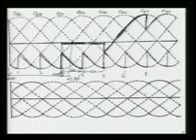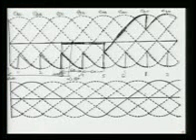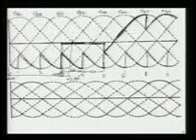So here 1 is fired, then even though 2 is fired, it won't affect its voltage because it will continue until 3 is fired. Once 3 is fired, it will automatically be 0. Now come back this side, because we have to draw the complete cycle. It is not completed, so we can come to the other side here and complete this. When 3 was fired, before that valves 1 and 2 were conducting.